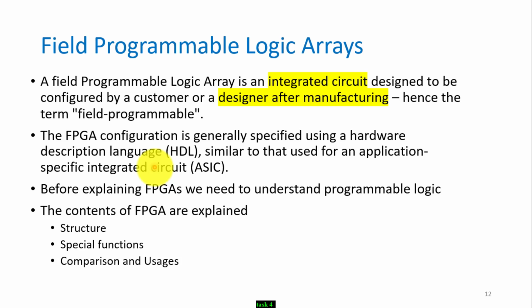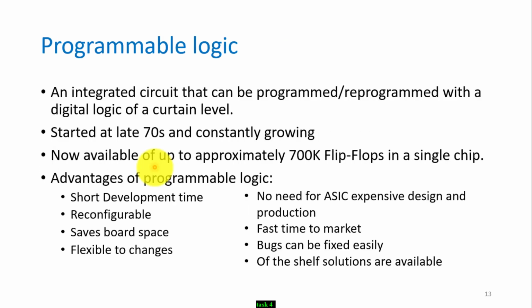Instead of going to the fabrication process, instead of creating an application-specific IC, which means this IC is only used for that application and is very expensive, we create an IC that can be programmed for any function, and at the same time, we can reuse it, reprogram it. This will make the cost very, very low. You want to create a system, you can create it on an FPGA and start selling the system on an FPGA instead of creating the application-specific IC, which is very expensive.